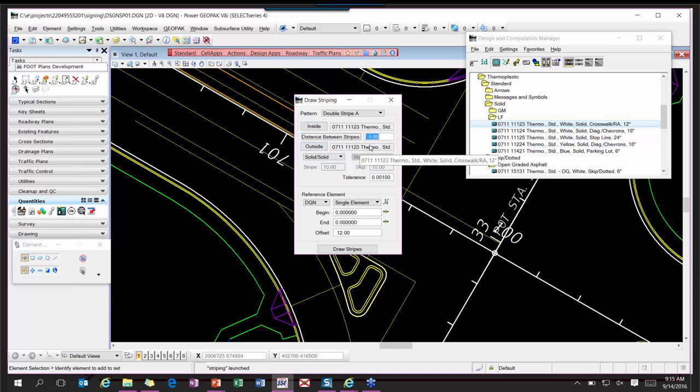For intersections, if you look at the index, it's a minimum of 6 feet between the lines, and we've got a 12-inch stripe. So from the center line, these lines are drawn at the center line of our stripes. So from center line to center line of my stripes, that gives me another foot. So I'm going to change this offset between those two lines to 7 feet. All right, they are solid, so I'm going to leave that as solid, solid.